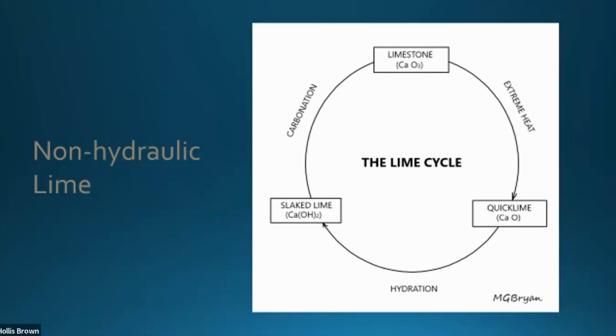Calcium hydroxide, the hydration that's in it, is locking out the carbon dioxide, which has been driven out through heat in this first part of making hydrated lime. So the heat drives out the carbon dioxide. It becomes what's called calcium oxide, which now has no carbon dioxide in it. Then when you hydrate it, that locks the carbon dioxide out. It can't get back in, but it wants to. Nature wants it to return to limestone, kind of like magnets attract us, the same thing.